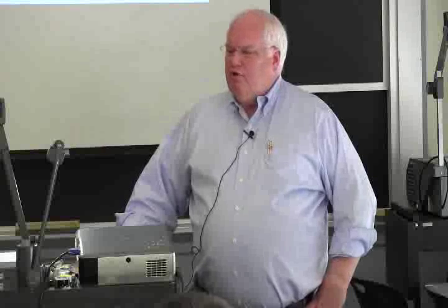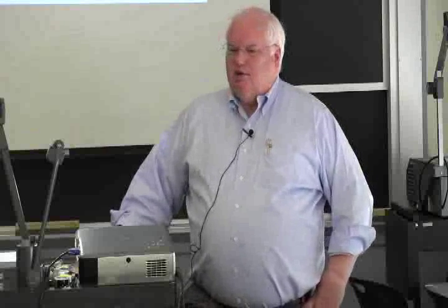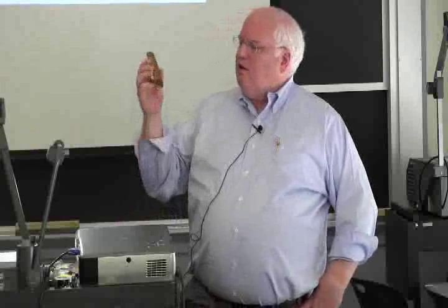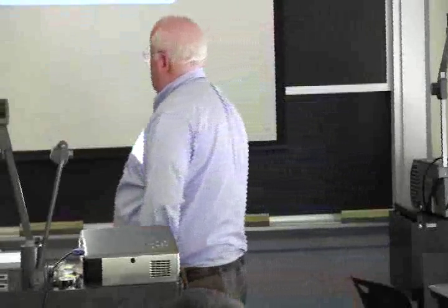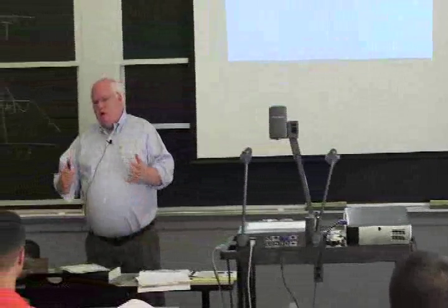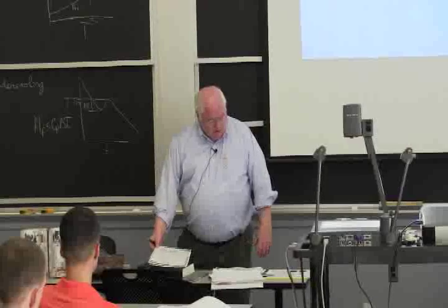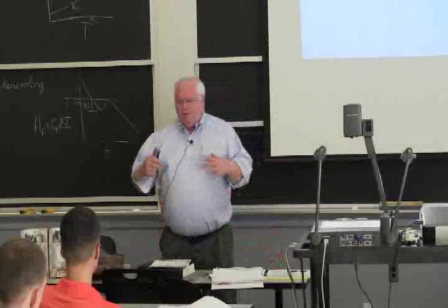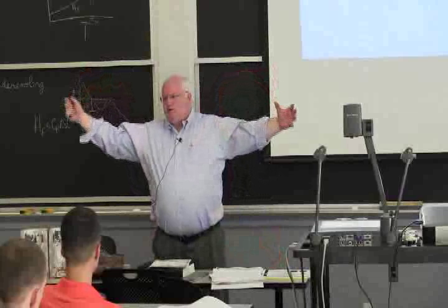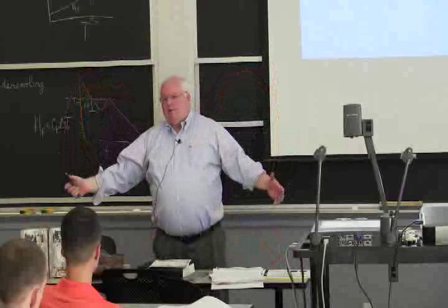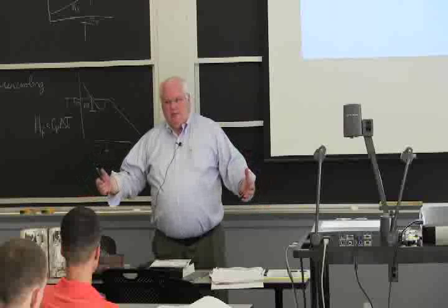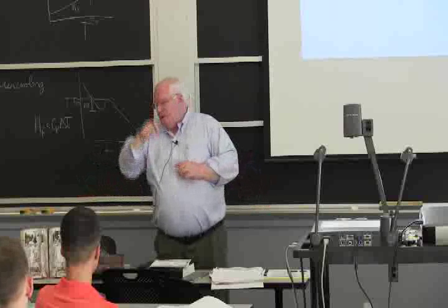But there are a few applications of making copper. I talked about this one, but there is Southwire, a firm, I think they're out of Georgia, somewhere south of Atlanta. And the Southwire process is, and that's what I was trying to find, and I still couldn't find it. I must have left it in my office. There was a picture of it, but basically the Southwire process is about a 6-foot diameter copper wheel that has a groove cut in it.